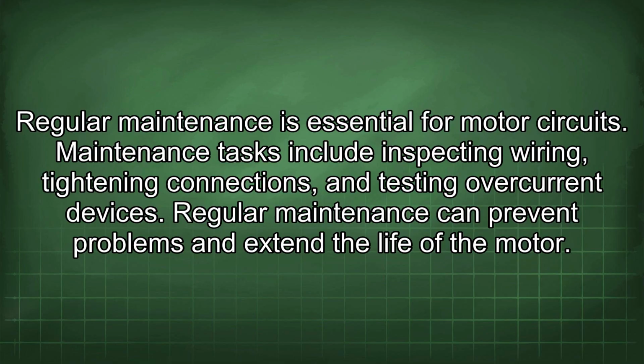Regular maintenance is essential for motor circuits. Maintenance tasks include inspecting wiring, tightening connections, and testing overcurrent devices. Regular maintenance can prevent problems and extend the life of the motor.